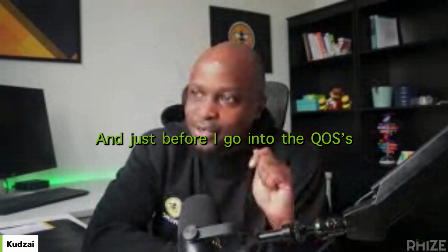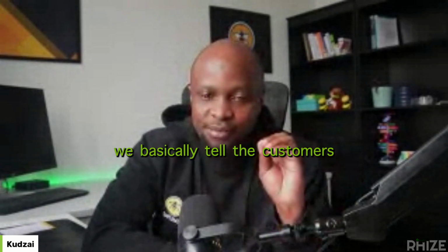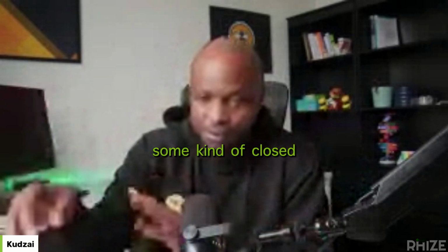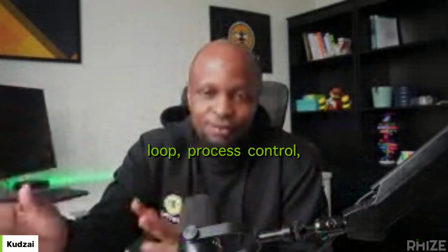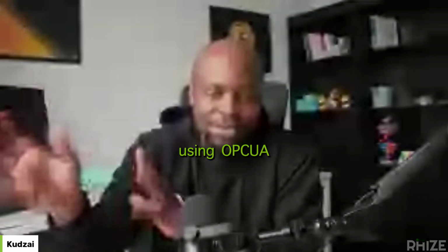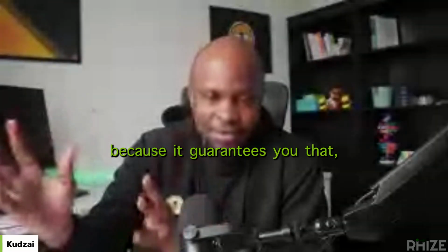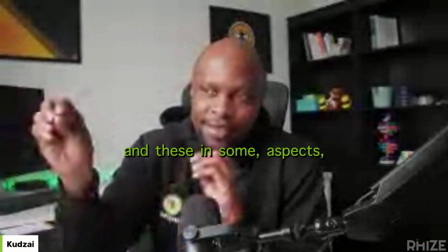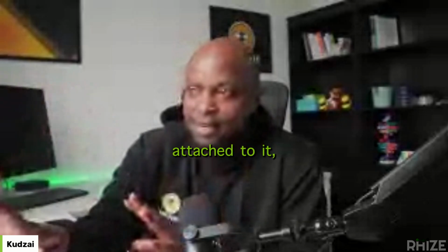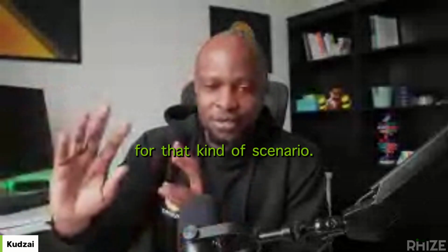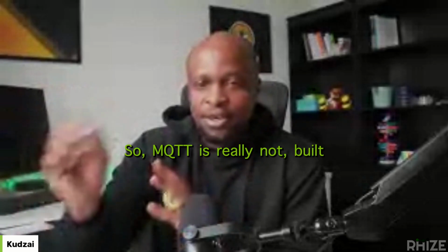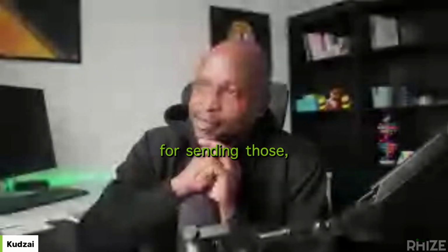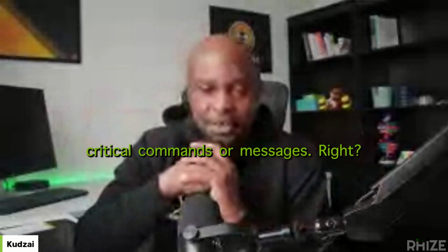And just before I go into the QoS, most of the time we tell customers that if you need to control your robot, or perform some kind of closed loop process control, you're better off using OPC UA or some other field-level protocol, because it guarantees you synchronized communication where you get the response and immediate feedback about what's happening, which is perfect for that kind of scenario. So MQTT is really not built for sending those critical commands or messages, right?